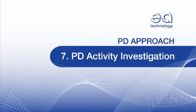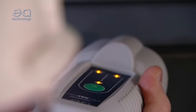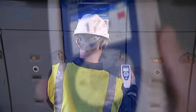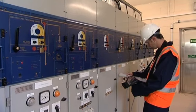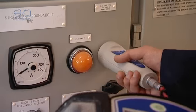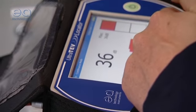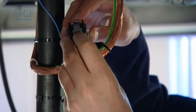PD activity investigation. So how do we locate the exact site of PD activity and investigate its magnitude and severity? Our Ultra-TEV range of handheld instruments will get you very close to the sources of PD, but for total accuracy and speed, use the Ultra-TEV Locator. It's a complete, portable PD investigation system that locates, measures, and records PD activity in all types of substation asset, including cables.